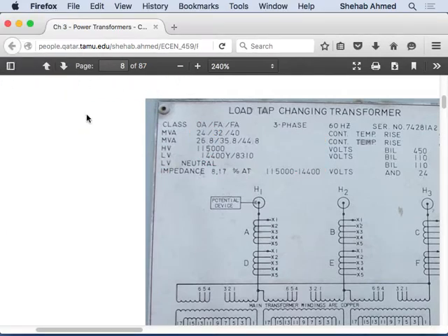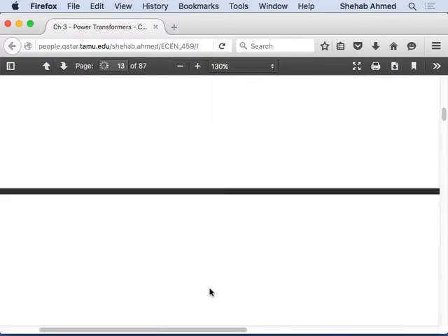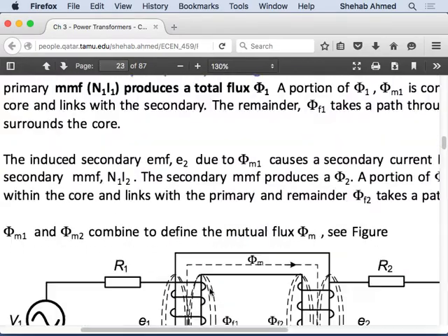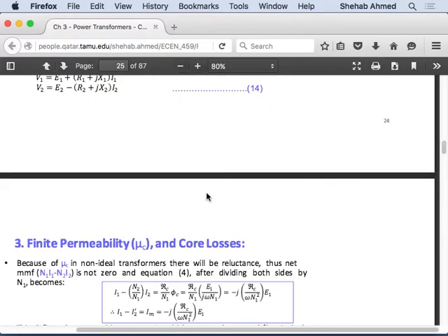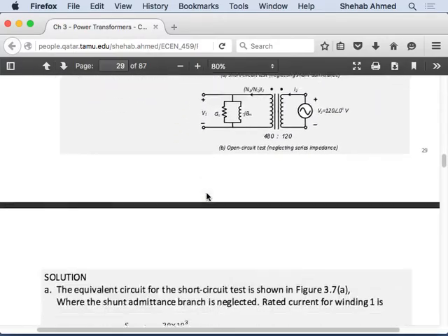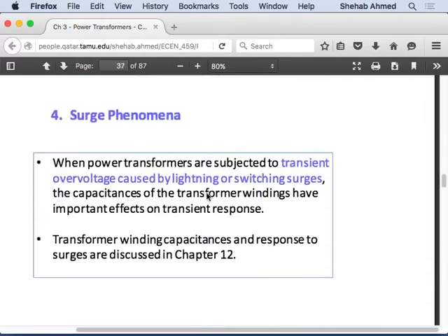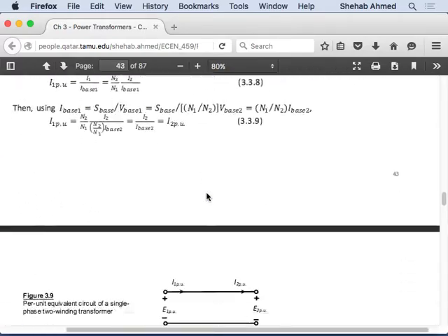Okay, so that is what we will talk a little bit about. It's called change of base. Because before we do that, I cannot build a big system anymore, right? We did an example where we had a specific piece of equipment, and we looked at this specific piece of equipment and converted its impedance to per unit, right? But I cannot now build a larger system without having multiple pieces of equipment,